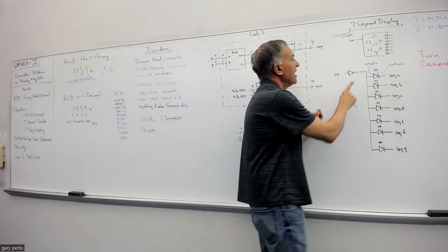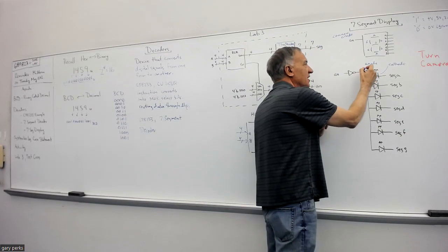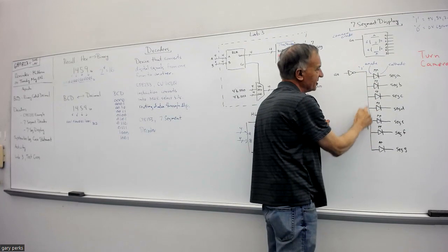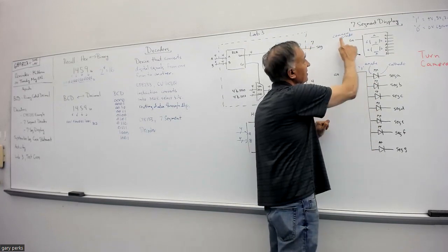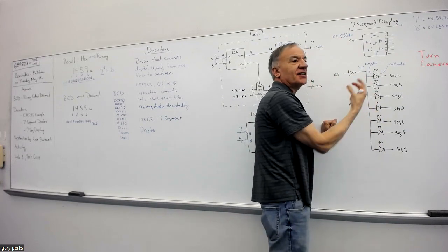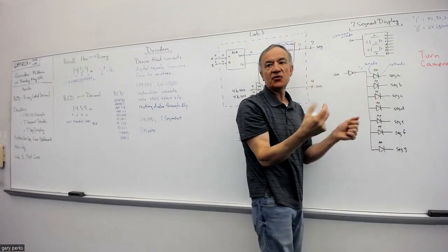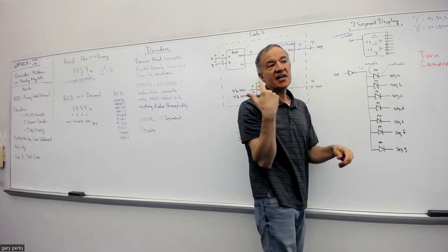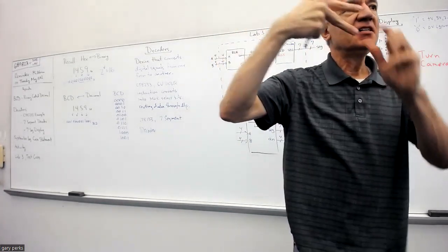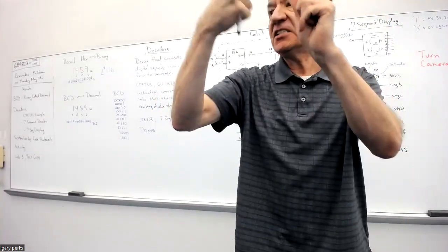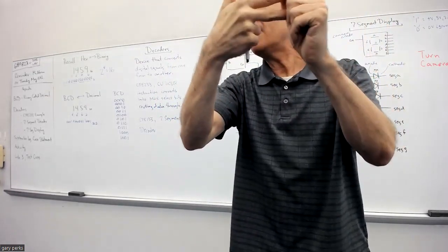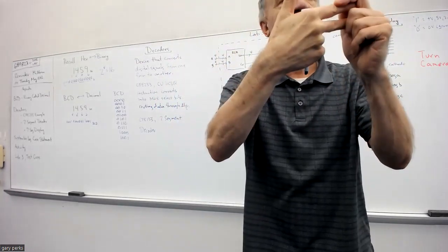Now, because of this inverter, in order to get a 1 where the anodes are, because you see this line here is connecting all the anodes together. That's why it's called a common anode, because all the anodes of the segments are connected to the same node, or connection point. As I mentioned earlier in the class, when you physically connect inputs of gates together, that makes the same value for those inputs because it makes it the same voltage.